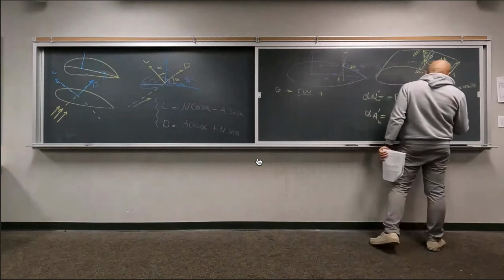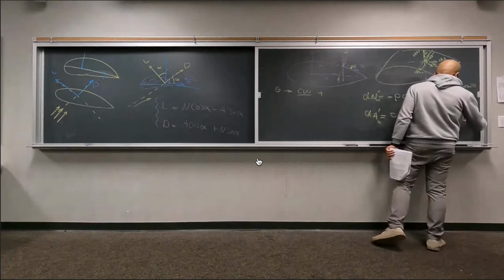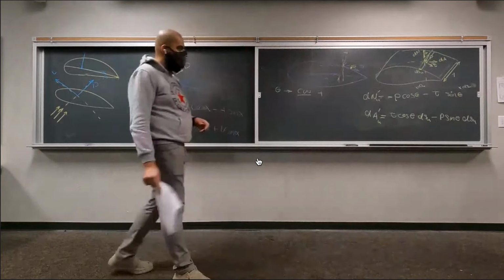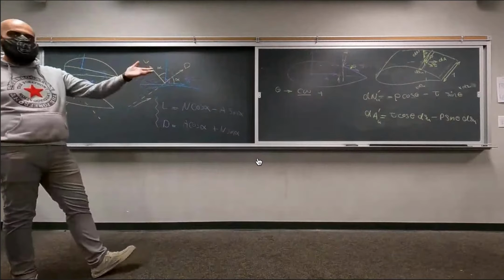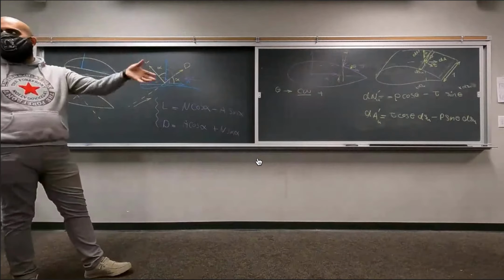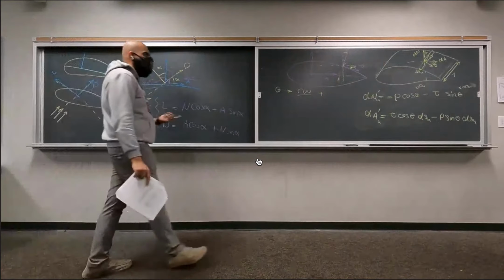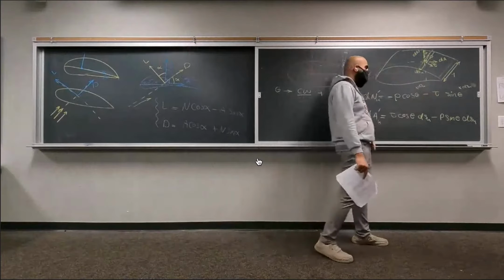DSU, we are going to get the negative P sine theta DSU. Right? The reason behind the negative P's is because of the direction of the force, not because of the cosine and sine relationship. Which is not the case for the negative sign and positive sign we see for the shear.